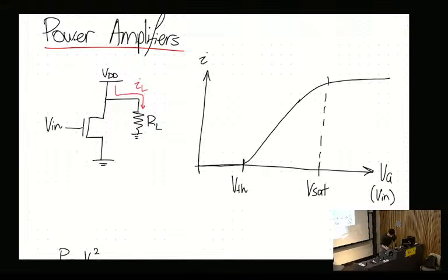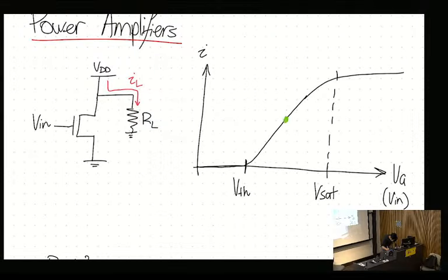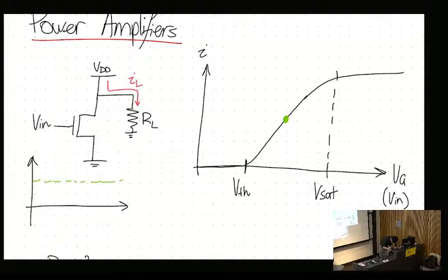As an example, if I bias my signal at the input so that, before even applying an AC signal, it has some default DC signal. So what this input signal looks like, if I just draw it, I'm biasing it by default with an offset, some VDC. Using the tap analogy, this would be if I turn the tap halfway and it's just running. And then what we do is we apply an oscillating signal around it.